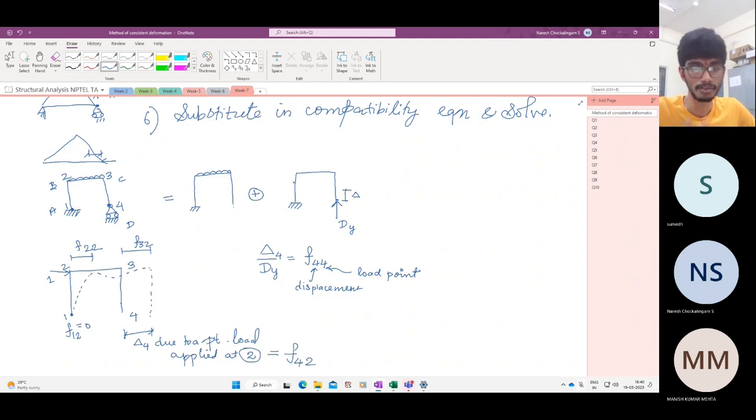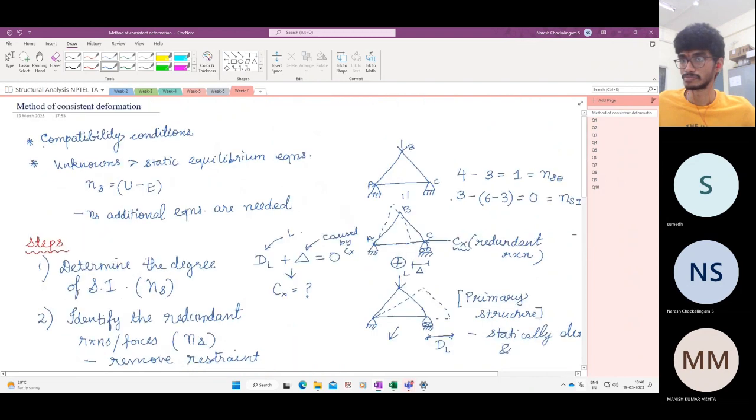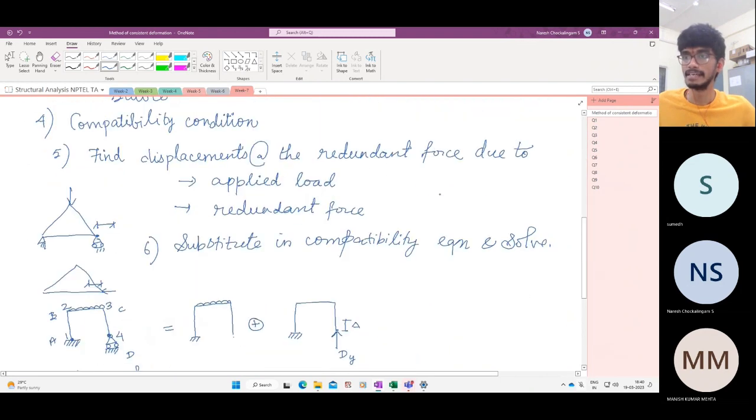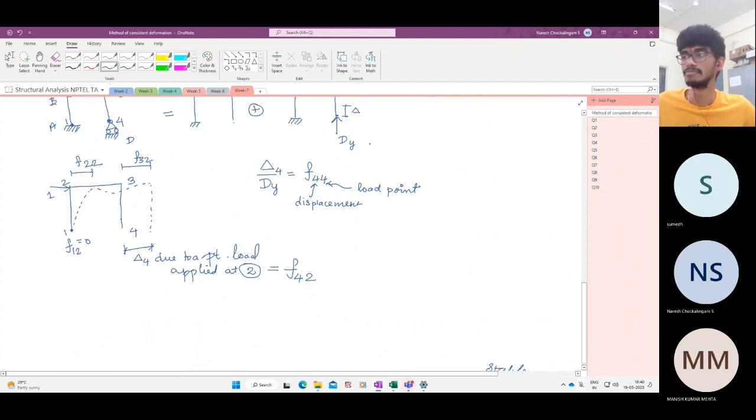So if we have some unknown loads or some known loads of a higher magnitude, the displacement is obtained simply by multiplying the flexibility coefficient by the applied load and then adding them all together. So that is very useful in our problems. I hope it's clear. It will become clearer as we solve some more of these problems.